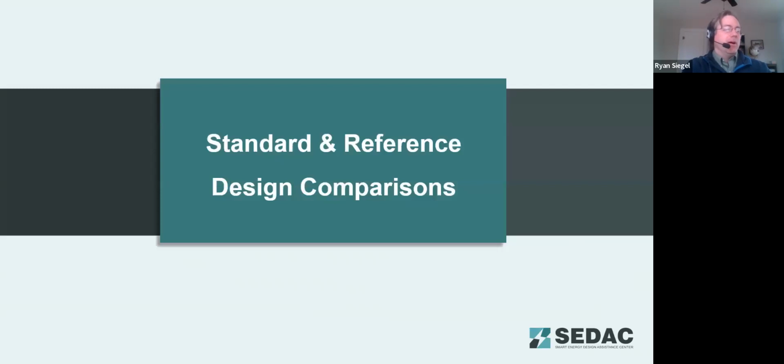With that, I believe we've got another poll here. How do the exceptions for standby loss impact ASHRAE versus IECC in the energy cost performance? ASHRAE can have more energy loss for hot water. ASHRAE can have less energy loss for hot water. ASHRAE can allow designers to take advantage of the decreased standby loss in the proposed model, increasing savings. Or there is no relative impact.